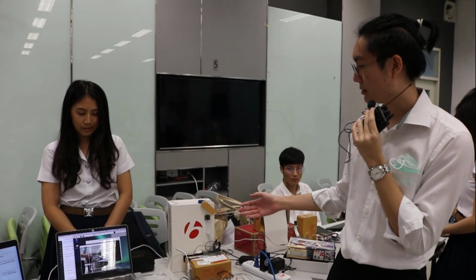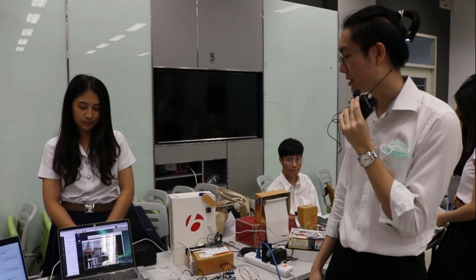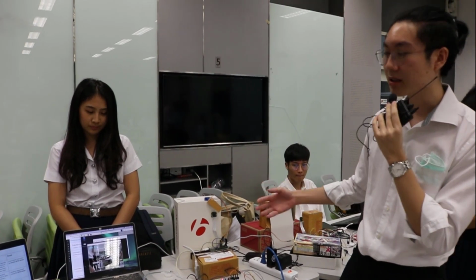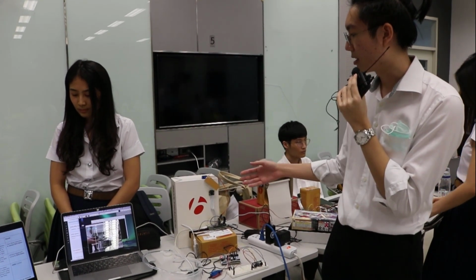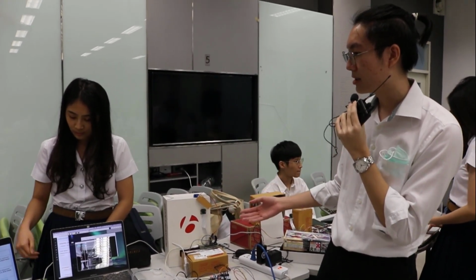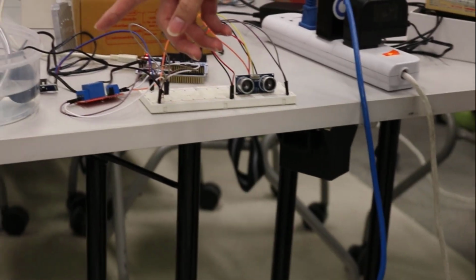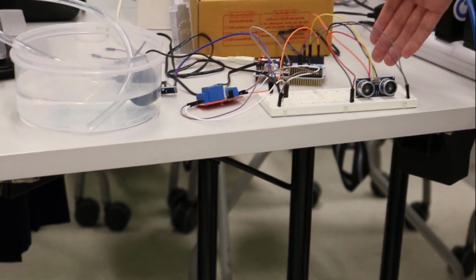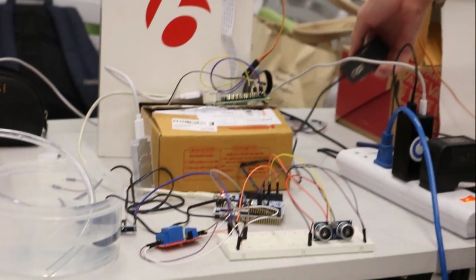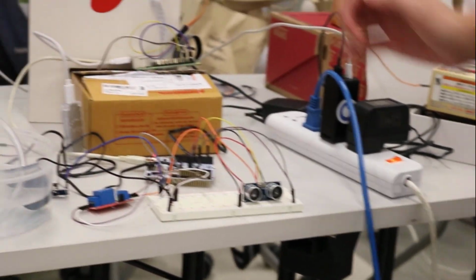So for the summary of work, when we got the machine learning model, it worked really well. But as I mentioned before, sometimes it thinks the same person is a different person, so the buzzer and door would work incorrectly. After we implemented the object tracking algorithm, it can know if it's the same person or not. And then we have the alcohol dispenser as well. Initially we had a problem that the pump didn't work because the board wasn't supplying enough voltage, so we added an additional external supply for it to work correctly.